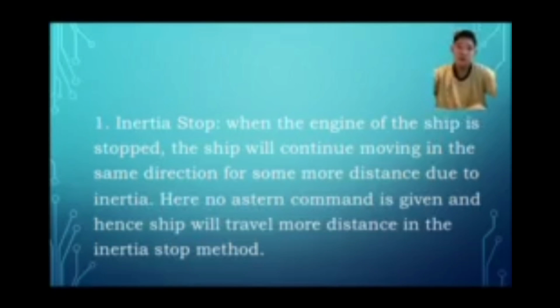Inertia stop: when the engine of the ship is stopped, the ship will continue moving in the same direction for some more distance due to inertia. Here, no astern command is given and hence the ship will travel more distance in this stopping method.